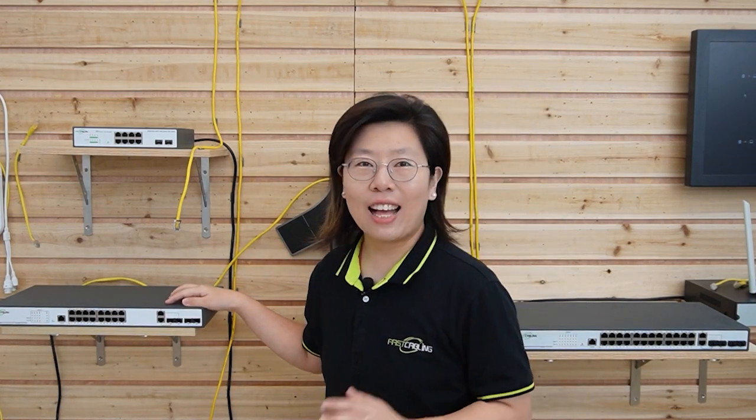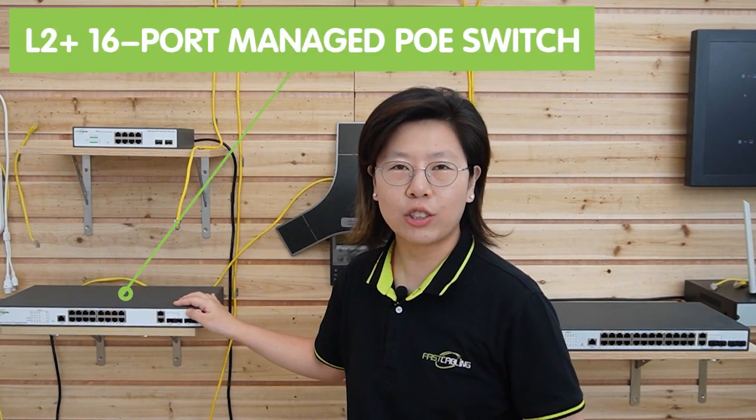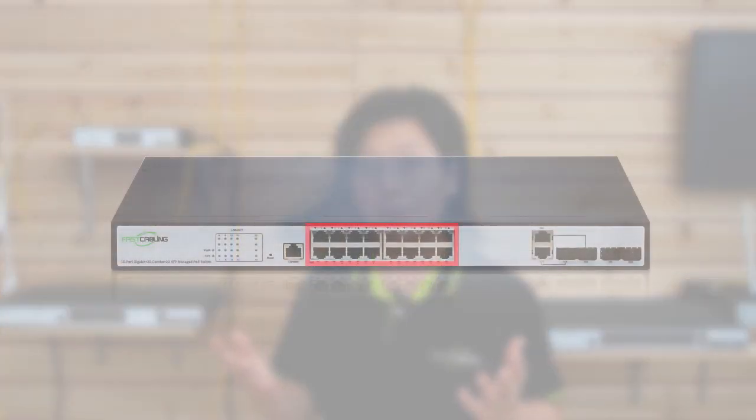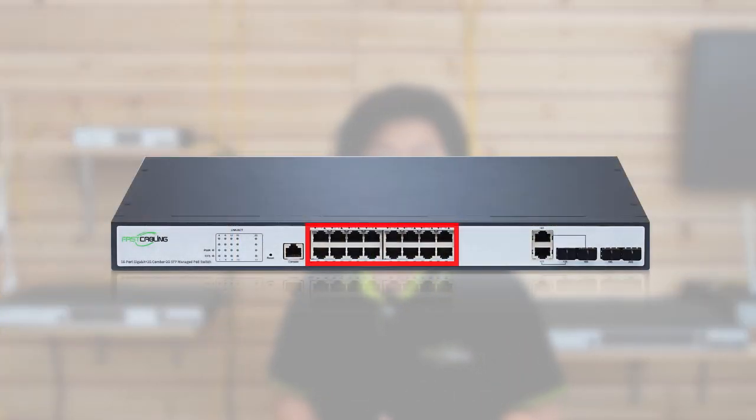Next, we have our 16-port L2 Plus PoE managed switch. Now this switch can provide intuitive and effective management and convenient maintenance for a PoE network system. It has 16 1 gigabit per second PoE ports, 2 gigabit uplink ports, and 2 1000 megabit SFP fiber slots, and is also compliant with IEEE 802.3 af and at standards, supplying up to 30 watts of maximum power output.